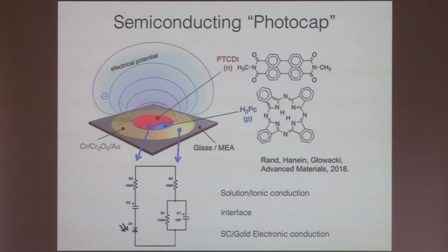So what people in this field have been doing is using electrodes that can be microfabricated or nanofabricated and can eventually be introduced to neuronal tissue, including to the eye. What people started thinking at some point was to use photosensitive systems. Silicon was a very obvious choice because silicon is a very good material for converting light into an electrical pulse. Silicon has been used, and there are a couple of devices based on silicon.